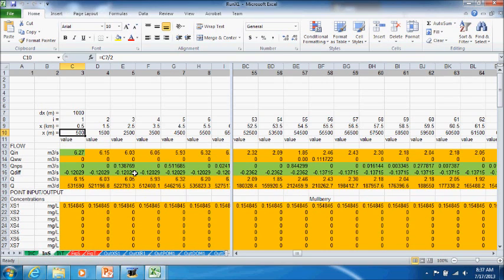For each segment, we specify the flow rate, and in this application, it's a relatively complicated setting, because we have withdrawals due to agricultural withdrawals. So what actually happens in this river is that the flow rate decreases as you go along the river, and then it increases again as the agricultural flows are returned to the river.